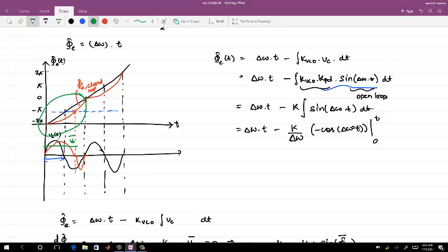Got the idea? You start at time t equals 0 with a certain delta omega, you start developing that control voltage, and before the phase error accumulates to 2 pi, you develop the DC control voltage required for locking in of the PLL. In this case, if delta omega by K is greater than 1, then you cannot develop that voltage, right?